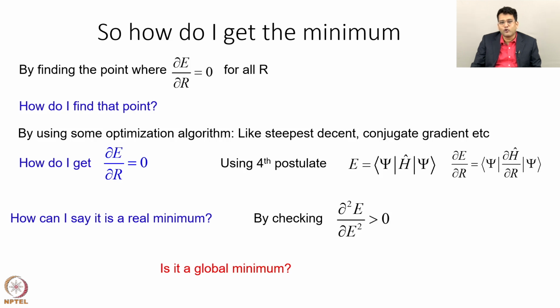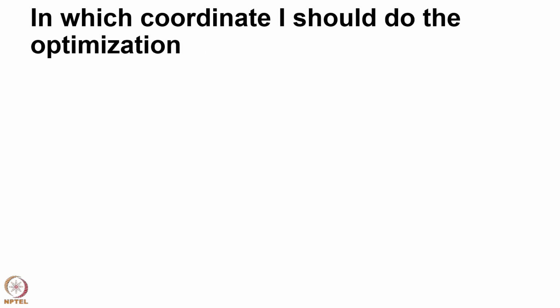So, to find the global minima, you need specialized algorithms. Orca has one of them, called the GOAT algorithm, and we will see how this algorithm works in one of the examples. In the case of general optimization, if my energy goes up in all directions and all my frequencies are positive, the only thing I can say is that it is probably a minima. Whether it is a global minima is very difficult to predict, and it is almost impossible to guarantee.